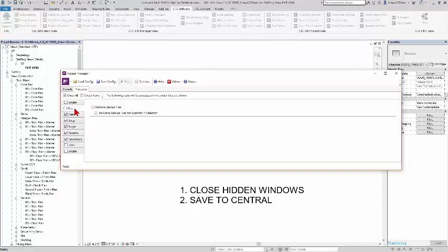You can also do some things if you're maybe working with a non-work sharing enabled project and you want to remove backup files and maybe exclude or remove all backup files that might not necessarily be explicitly included in the selection that you've made, like just additional backups in that folder. You can have this go ahead and delete those if you want to. In my case, you can see I've turned off those two options. I'm not going to use them.